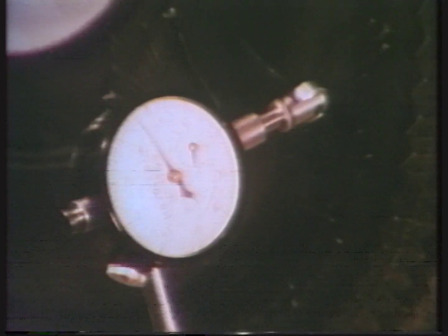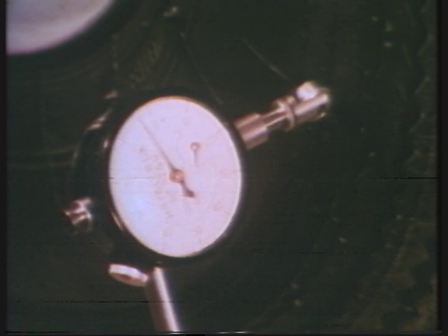Both kinetic and dynamic unbalance can be involved. So inflate tires to 40 pounds per square inch. Jack up the front of the car and reduce hub end float to 0. Recheck tire fitting beads, then check radial and lateral runout of the tire. You're now working to tight limits. Excessive runout may be due to out of round tire, wrong position on wheel or hub runout.